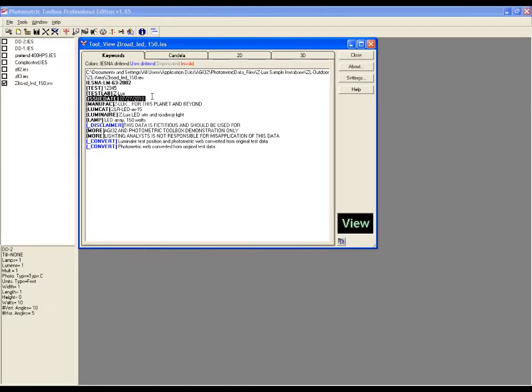And other keywords are also available, which provide useful information but might not actually be required, such as ballast. Ballast is an example of a keyword that you'll sometimes see, but it isn't actually required. Some luminaires have been around a long time and were tested prior to 2002, which is the most recent update of LM-63. Some of the older reports do not fully comply with LM-63-02 as far as the information that they contain. They might be missing the issue date, or they might be missing the test lab name. Those things are required now.